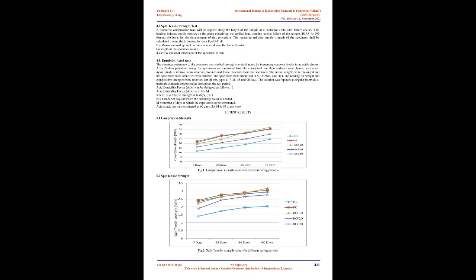It is also called self-healing concrete as the healing process is independent and autonomous. The bacteria become active as soon as they get in contact with water and eventually precipitate calcite, facilitating the filling of minute voids generated on account of the physical structure of the constituents of concrete. This process takes place as long as water is available.